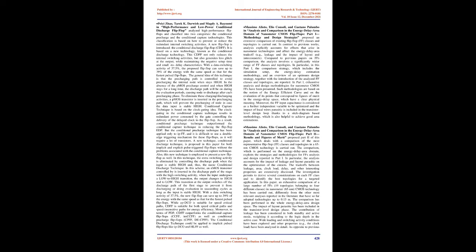Massimo Aliotto, Elio Consoli, and Gaetano Palumbo, in "Analysis and Comparison in the Energy Delay Area Domain of Nanometer CMOS Flip-Flops, Part I: Methodology and Design Strategies," propose an extensive comparison of existing flip-flop (FF) classes and topologies. In contrast to previous works, the analysis explicitly accounts for effects that arise in nanometer technologies and affect the energy delay area trade-off, e.g., leakage and the impact of layout and interconnects.